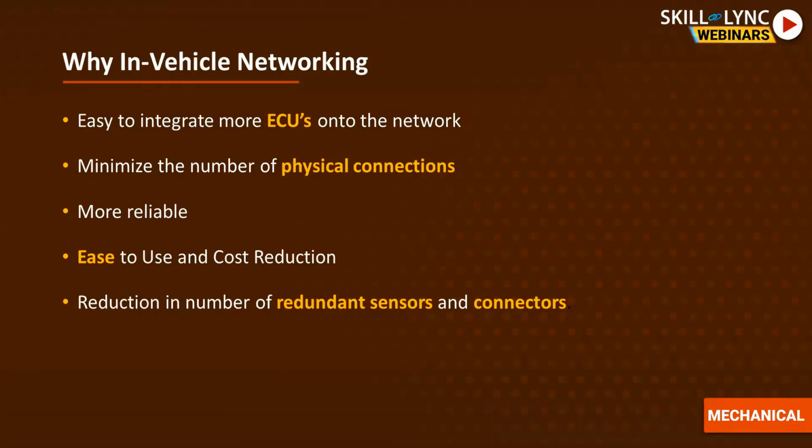which you may have noticed if you sit inside the car. The OBD will most probably be down by your seat, or otherwise down by the steering. There will be a socket, like a charger socket, and there will be pins inside that. 16 pins will be there, where you can connect your tool and get the data out of the car. So basically, the complete wiring harness you have seen will have one output, the OBD, and the car data can be taken out from that.